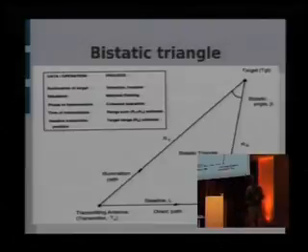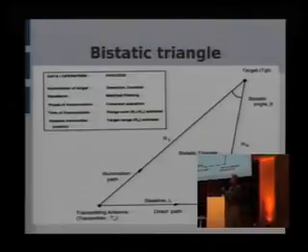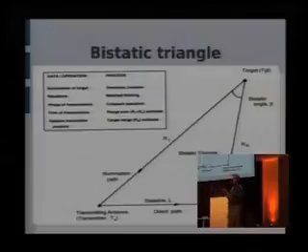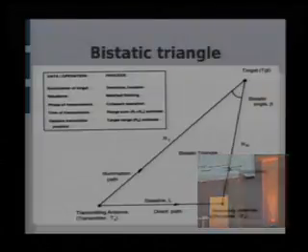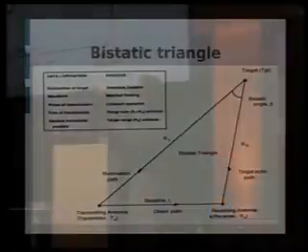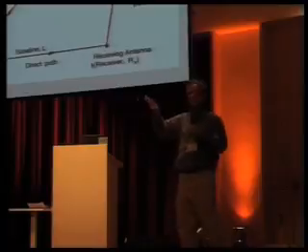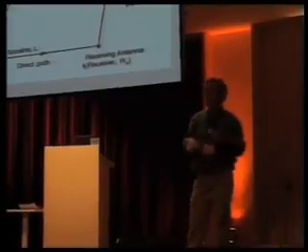Likewise, when you look at the Doppler shift in a situation like this, normally you think of Doppler as the change in the path length. Well, in fact, it's still caused by the rate of change of the total path length. But again, you don't know if the R_T path is shortening or lengthening or the R_R path is shortening or lengthening. So it's a little more complicated math than in the monostatic case.